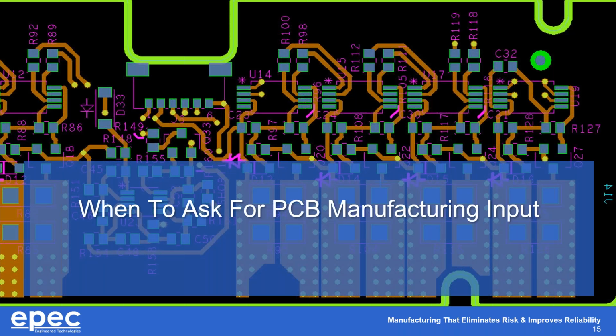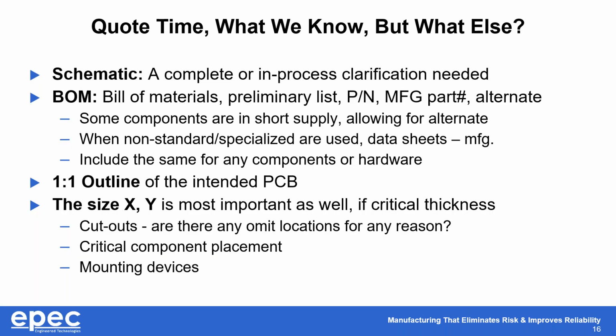So as I said, when to ask for PCB manufacturing input, for us the answer is after electrical engineering has completed the concept. Once you have your schematic completed or nearly completed, there may be some clarification needed. Your BOM, once that's completed, we need the part number, the quantity, manufacturing part number, and if an alternate is going to be allowed.